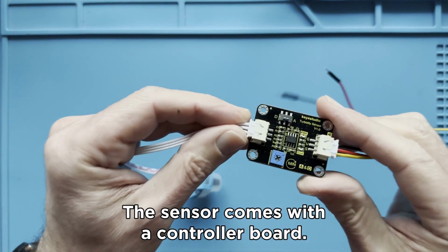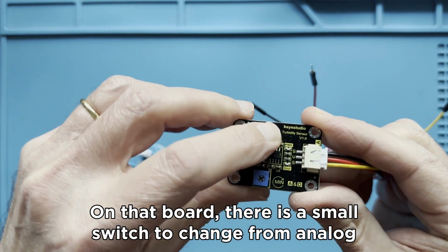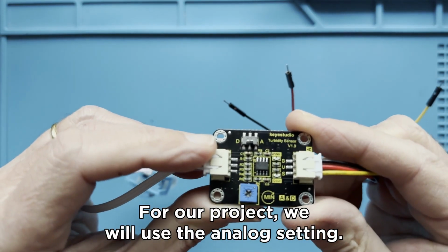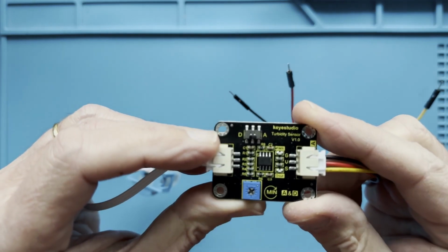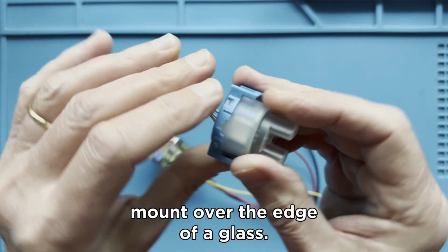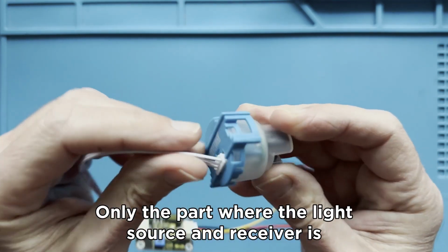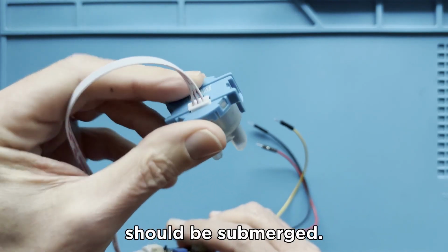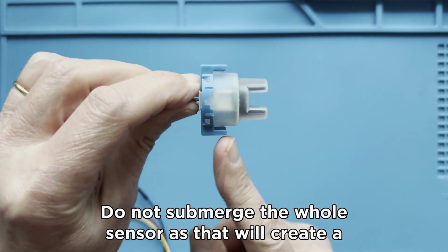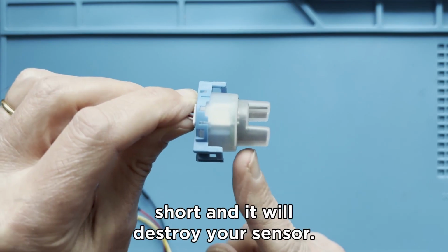The sensor comes with a controller board. On that board there is a small switch to change from analog to digital output. For our project, we will use the analog setting. As you can see, there are clips on the side of the sensor to mount over the edge of a glass. Only the part where the light source and receiver is should be submerged. Do not submerge the whole sensor, as that will create a short and it will destroy your sensor.